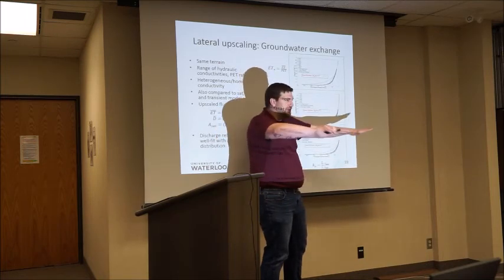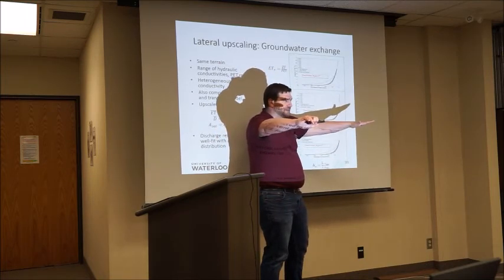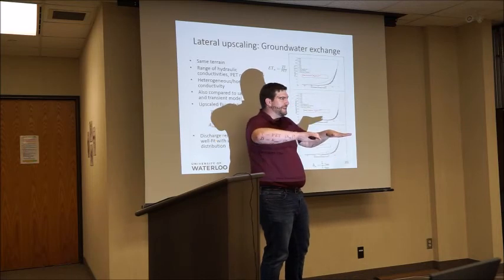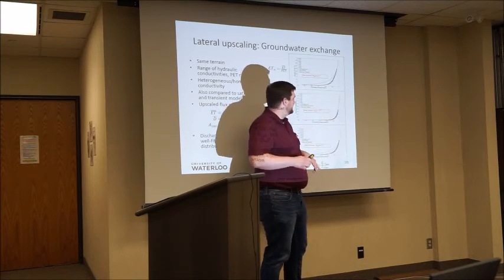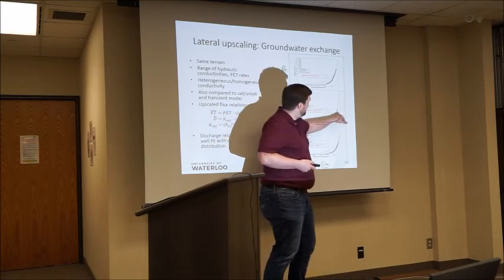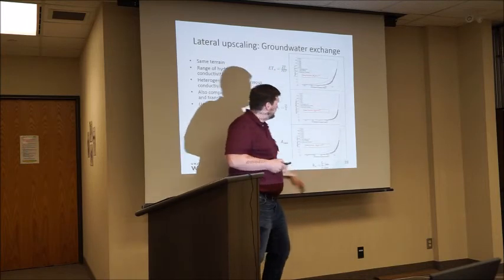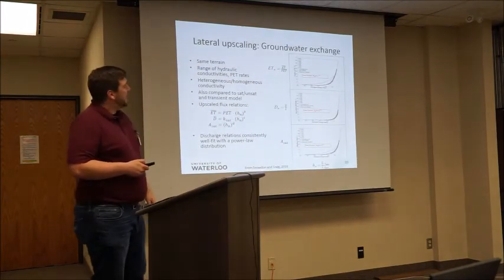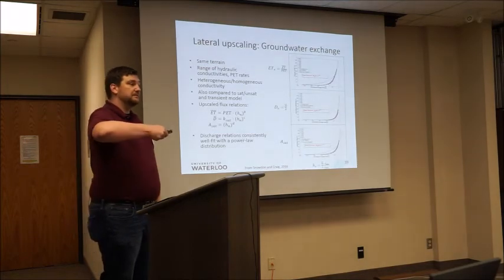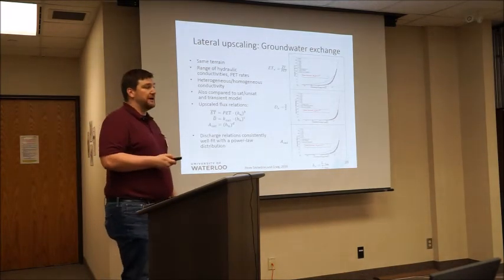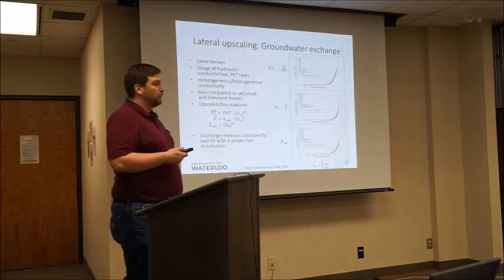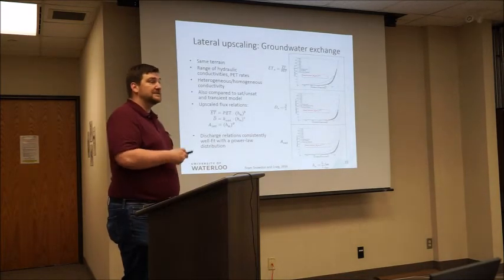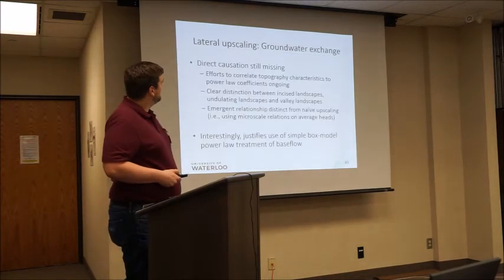So if you treat it as an equivalent average elevation surface and then the water table hits that, you can't even calculate the steady state discharge. It doesn't make any sense. But again, you collapse all along the same curve. And this is inferring from the microscale model. This is a lateral flow process, and we back out the emergent behavior.